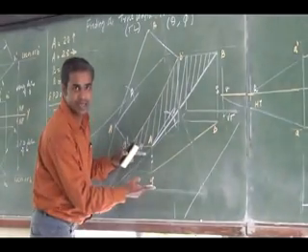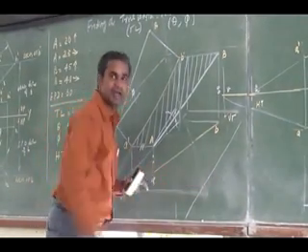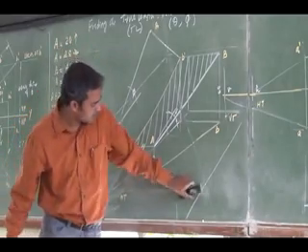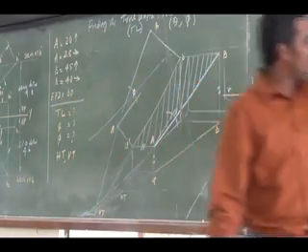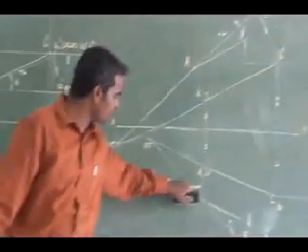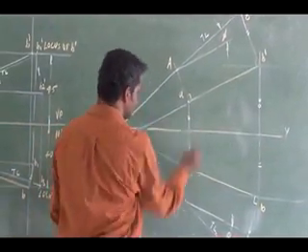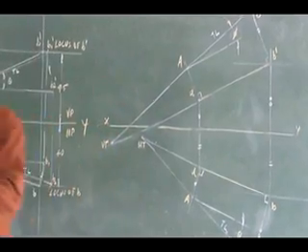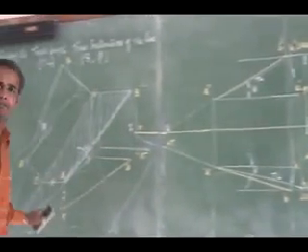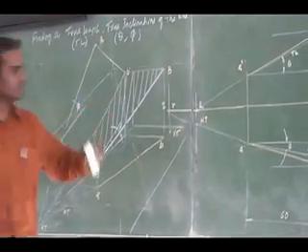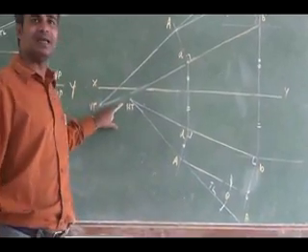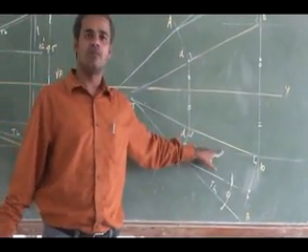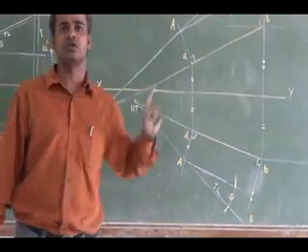I can rotate this and align it on the horizontal plane. Whatever I get here is going to be the perpendicular, and in front of it I will mark the above distance here. Using that I can get the original line again. In the same fashion, the original line I will have is AB, and that will again give you the true length. Extending that original line to where it meets the top view gives the location of my horizontal trace, right?